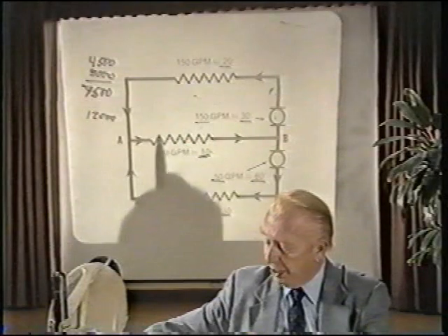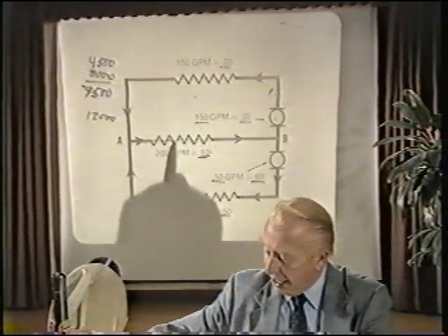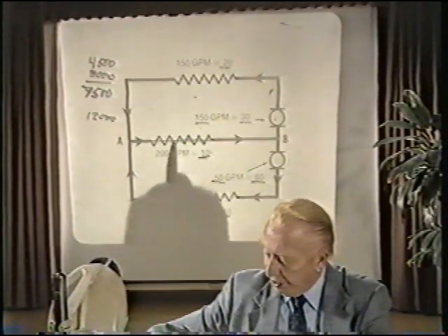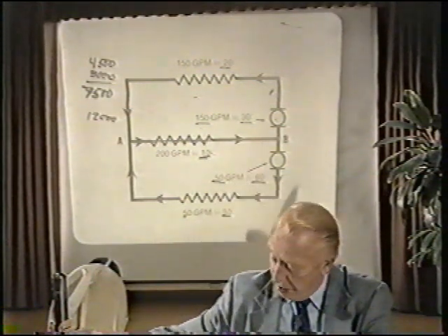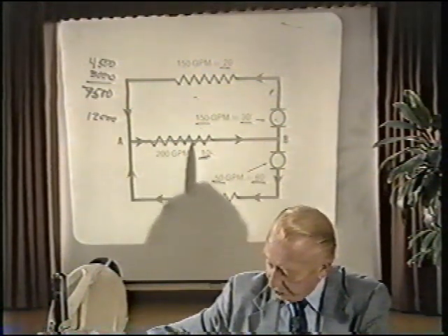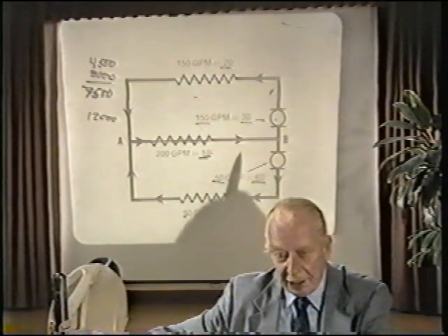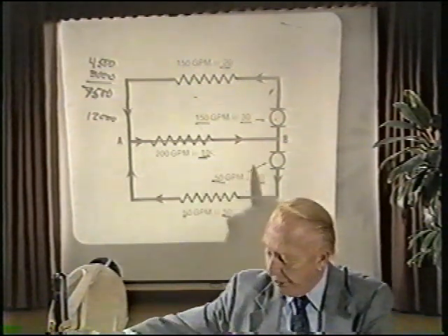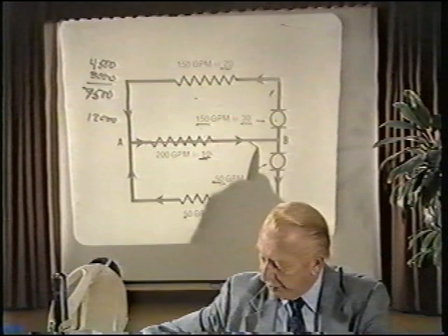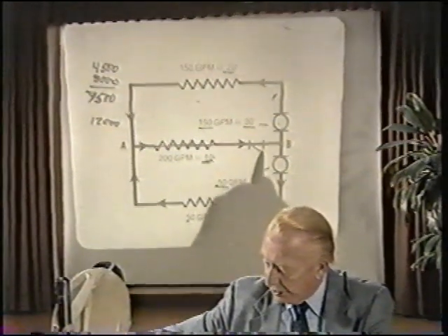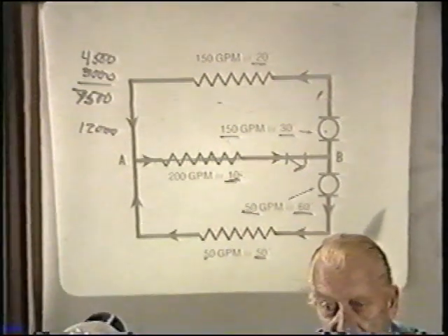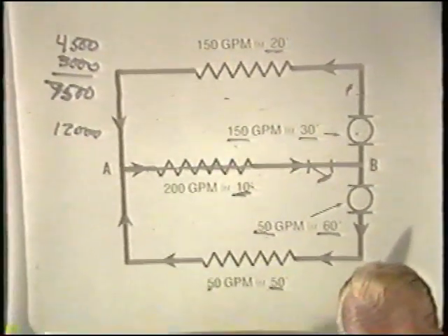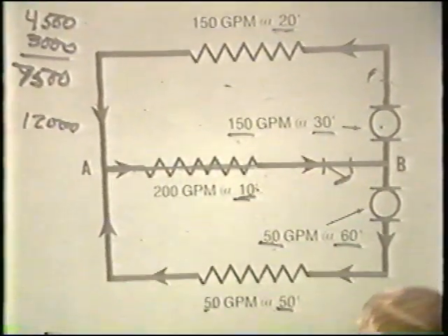And the potential problem is caused by the pressure drop in the piping common to both circuits. For example, if we have a variable head loss in that common piping, as from a single strainer, we can cause trouble if that strainer becomes clogged.